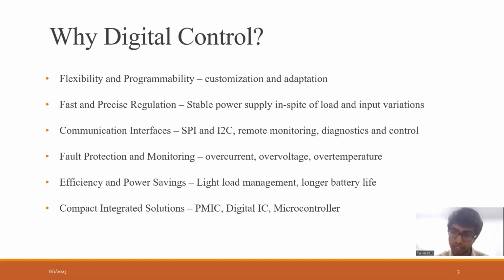So suppose an overcurrent has happened, then it must disable the inputs. Suppose there's an overvoltage, what should it do? If the temperature is rising, what should it do? As well as, suppose there's a dip in the input voltage, then what must it do? Because when such anomalous situations happen, it would harm the application. And so what would be the suitable thing to do in that situation?